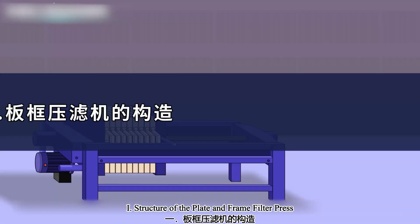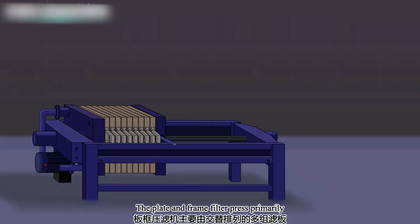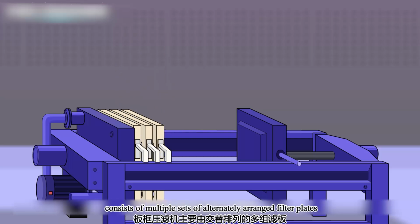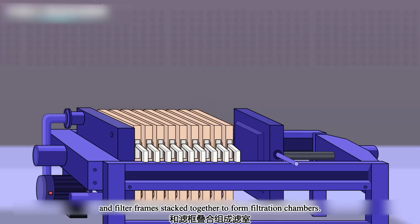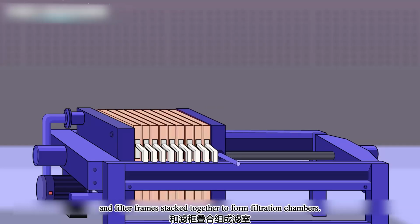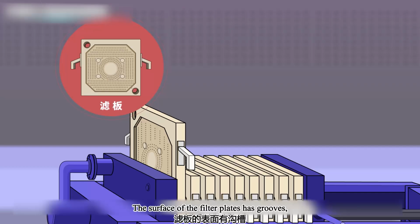First, structure of the plate and frame filter press. The plate and frame filter press primarily consists of multiple sets of alternately arranged filter plates and filter frames stacked together to form filtration chambers. The surface of the filter plates has grooves, with protruding areas used to support the filter cloth.